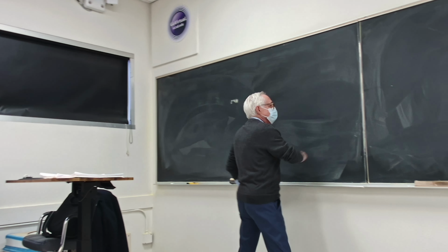And for the steady state situation, imagine continuously flow comes in, flow goes out. Therefore, no change inside the control volume. Therefore, dE control volume by dt is 0 if I have a steady state. Okay? And this is the energy rate balance.